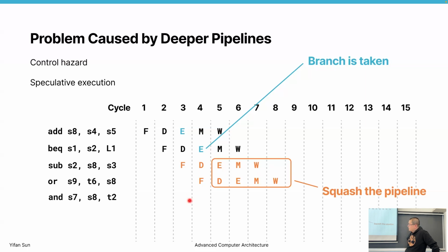Now for a 5 pipeline stage, this seems simple because we probably only need a few reset signals to reset a few set of registers. But there are many corner cases. What if you have already written back an instruction, right? Sometimes that can happen when we talk about wider pipelines.